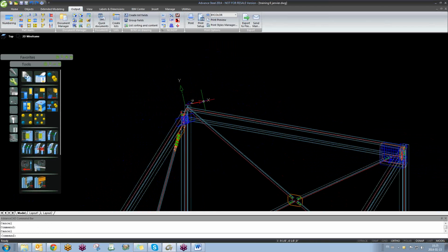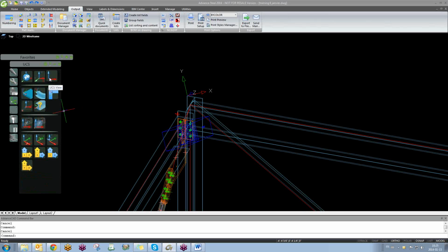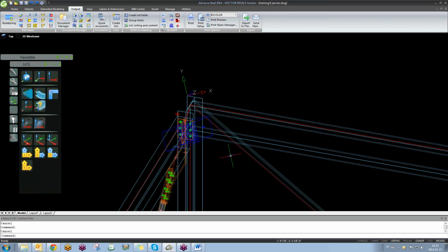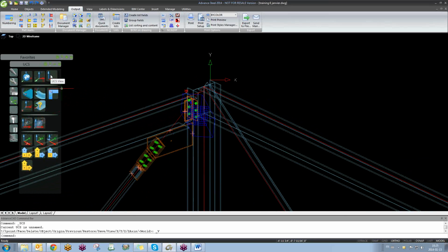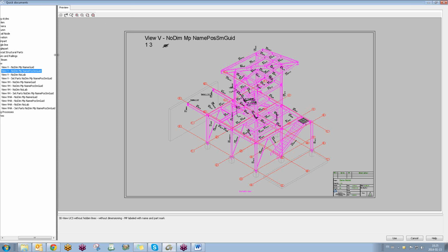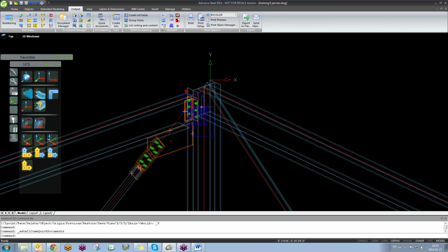So you change the UCS to... Yes, the key step is to change the UCS here, UCS at the view. Make yourself on the right view and put your UCS on view. After that, if you just want it to be like this without creating a camera, go here under view, the last one, or create a camera. Seems to be good.